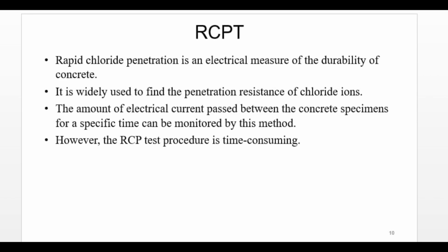The RCPT is used to assess the durability of concrete and to ensure the new concrete meets quality control standards. The chloride ions can cause the concrete to deteriorate and can destroy the protective layer on reinforcement steel. So this RCPT test uses a specialized instrument to apply the electric current and to measure the resistance of the concrete.